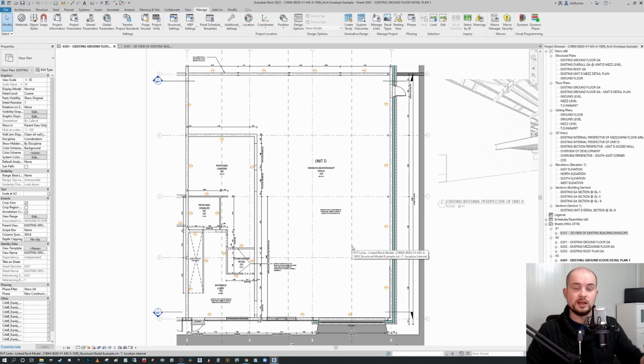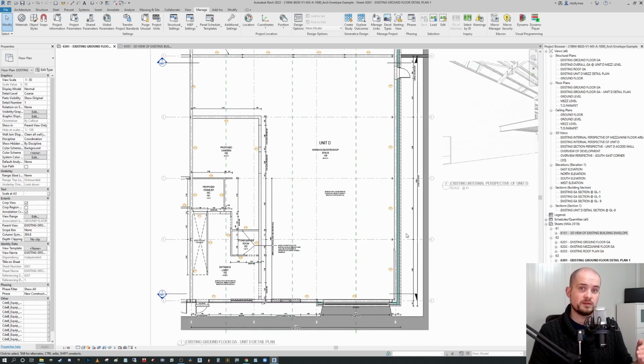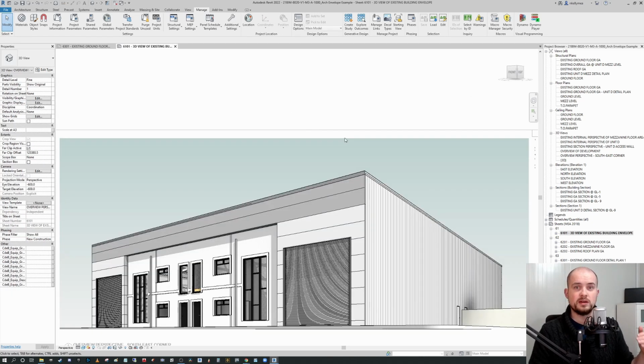And as you can see, the model restores, but through the element ID system that Revit has, it's actually retained the association of the tags within the host model to the link file, even though the link was temporarily unloaded. Okay, so that's a really, really useful feature. It's particularly important for larger firms who reference multiple files to put together their actual drawing packs.